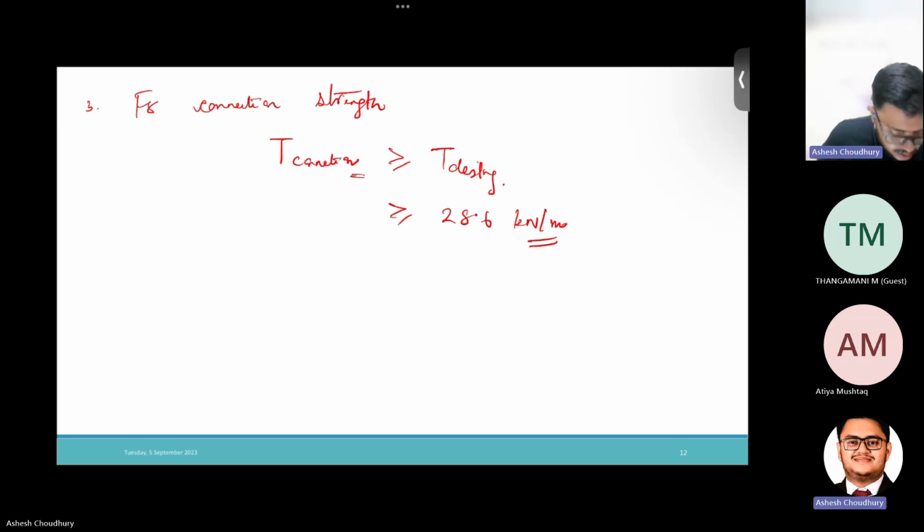All right. Now this was just the design, the stabilization design, the mechanically stabilized earth design. Also in case of these walls, we need to take care of the drainage. In our case, we did not consider any water pressure in the calculation. We are considering that the soil is dry. So what if it rains and the soil becomes wet? In that case, we need to allow for proper drainage of water.